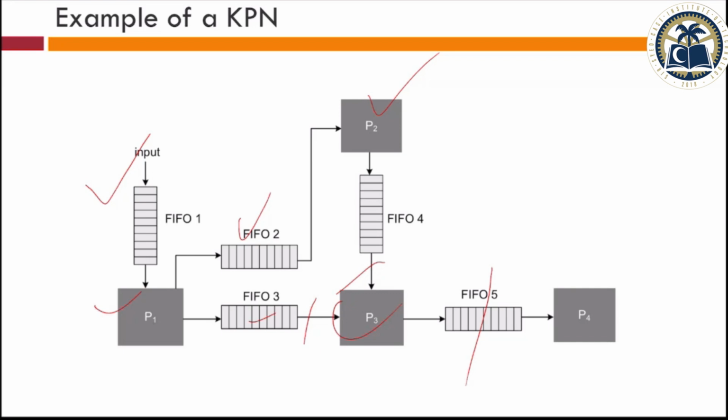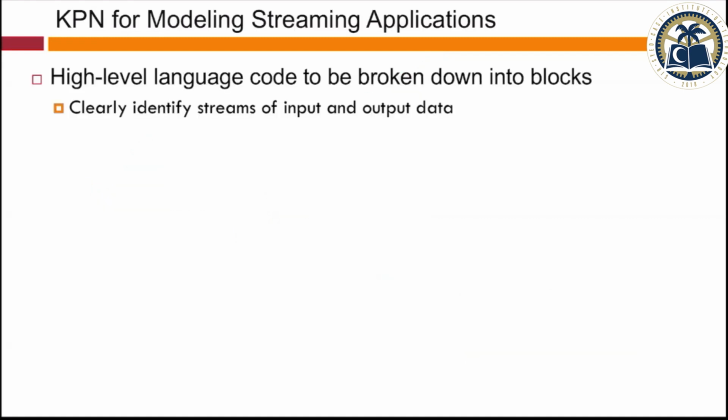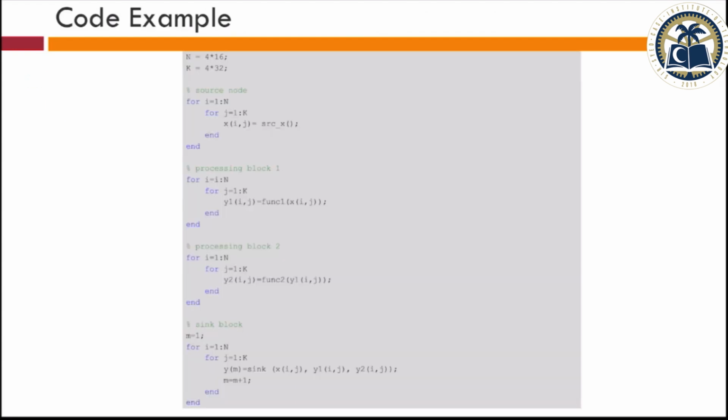Okay? A simple system level design without you really worrying about how to match up the different data rates. But in any interesting architecture you design, you are always going to get into this: every block would require a different number of samples, and it will usually not be an exact multiple of what the previous block is. You have to cater for that, whether you are doing it in software or in hardware.